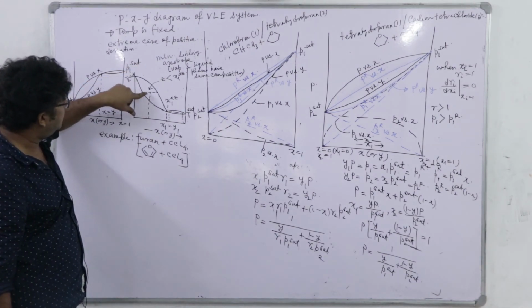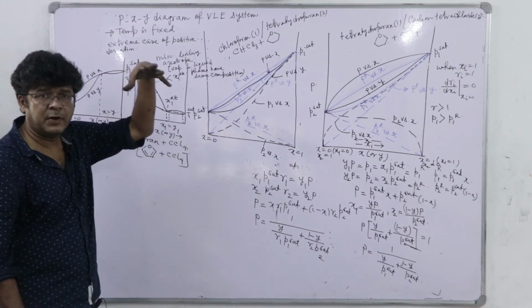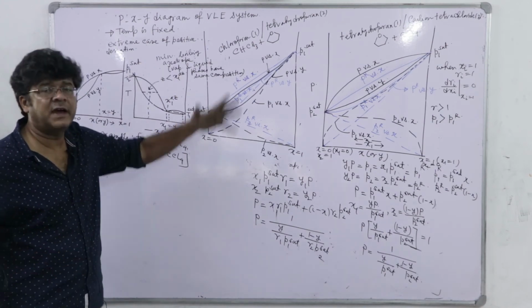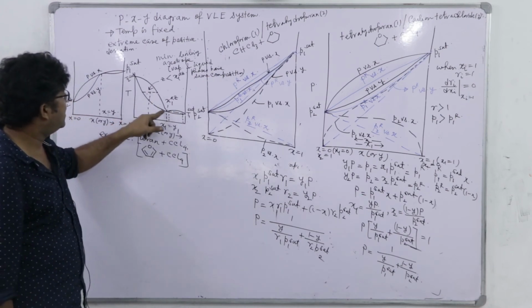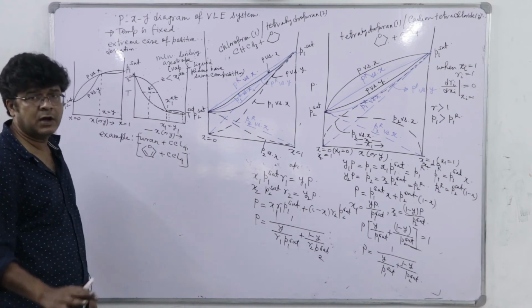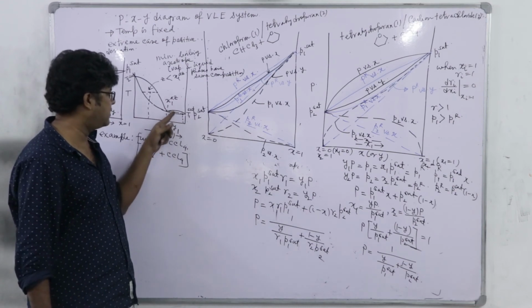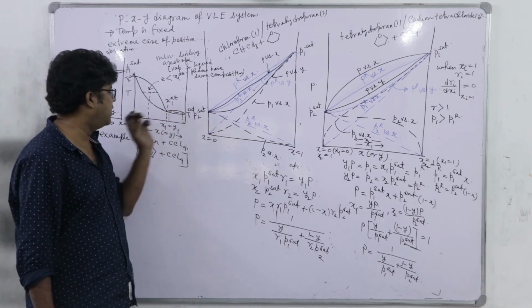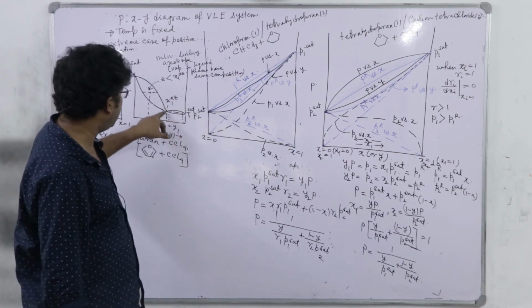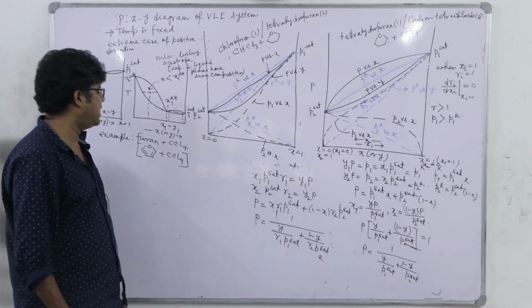So, if it is being fed, we will see later in mass transfer that if this feed is being fed to a continuous multi-stage distillation unit, and let us suppose we can achieve infinite separability upon introducing an infinite number of stages in this distillation column, as a top product we will have the azeotrope, as a bottom product we will have the pure component too. Whereas here, if I give the feed here, though it is a theoretically possible condition, I will have these two products, one will be the pure one, another will be the azeotrope. Okay. So that's the idea of minimum boiling azeotrope.